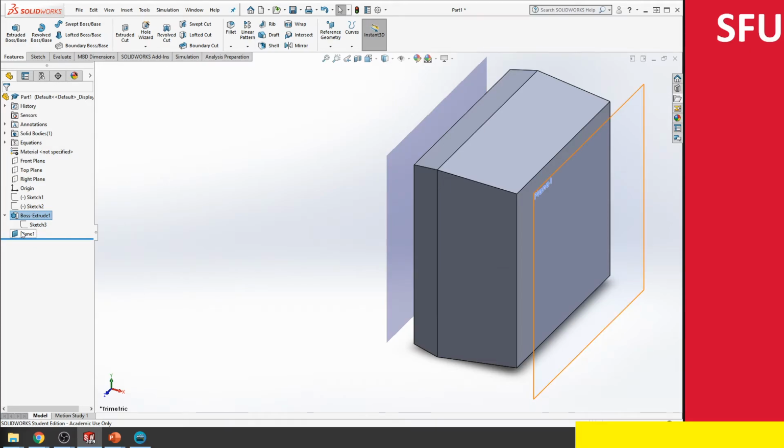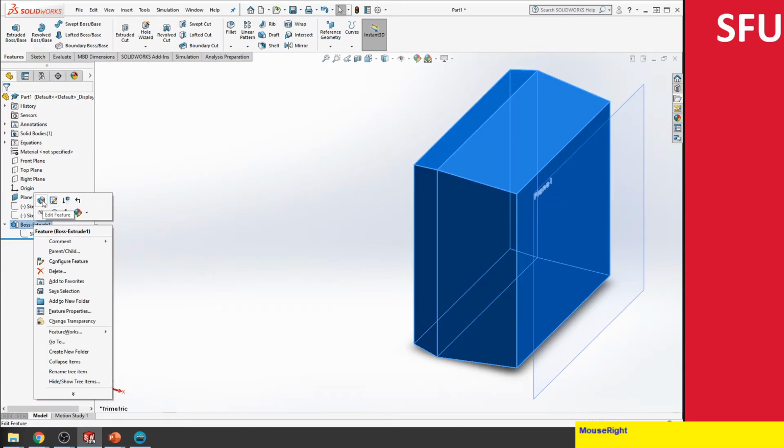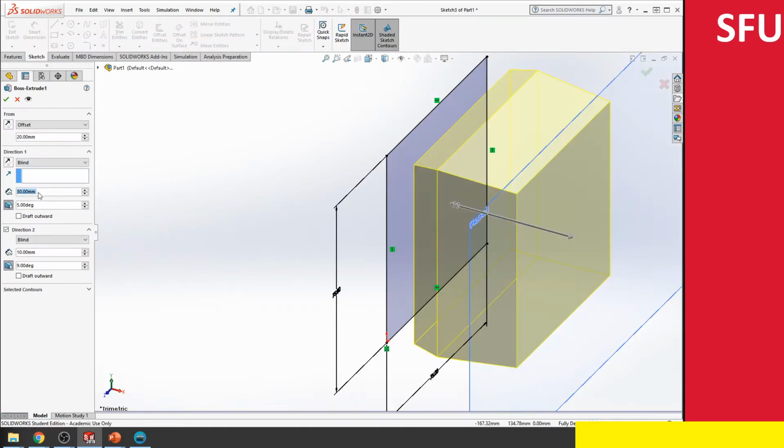So what we do in that case is we can move the plane one that we created anywhere above it. You can't move it above the right plane because it needs the right plane as reference, but you can move it just below the origin over here. Now if I edit, essentially we are rewriting the history. If you think about it in a kind of weird way, you're taking a second floor and trying to put it under the first floor and restacking the whole building so that you can use the first floor as a reference.